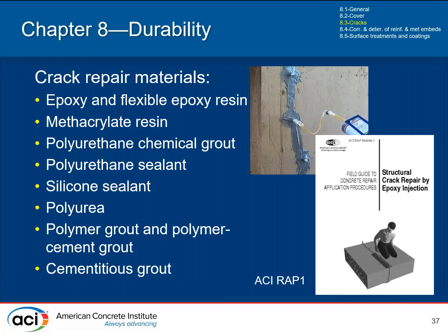But again, crack injection is obviously an important way to address cracks, and you can look at epoxies, which are rigid and provide structural performance if that's what's necessary. But if it's not necessary, there are some more flexible approaches, things that can be injected, such as polyurethanes. When you're evaluating repairs and evaluating the cracks, you should also be thinking about maybe the best way, if you have a lot of them, being a coating system or something like that.